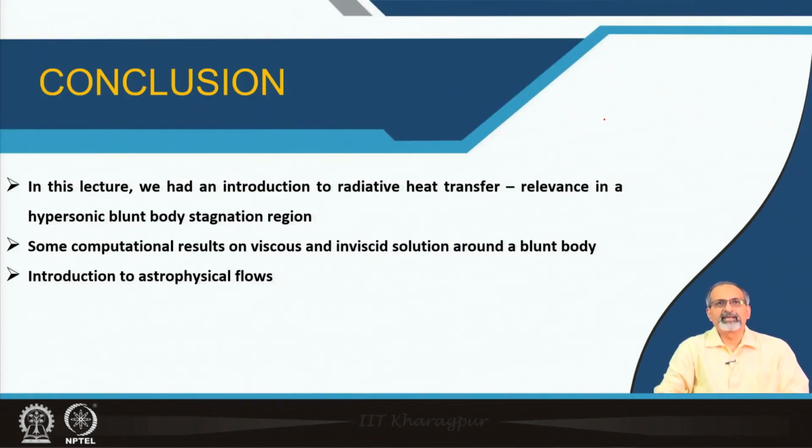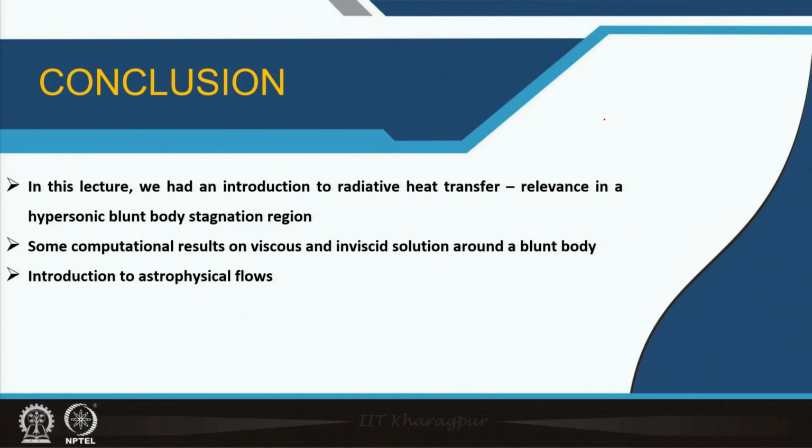Let us conclude by saying that in this lecture we had an introduction to radiative heat transfer, and we tried understanding the relevance in a hypersonic blunt body stagnation region. Some computational results on viscous and inviscid solution around a blunt body were discussed, and we ended by discussing an introduction to astrophysical flows.